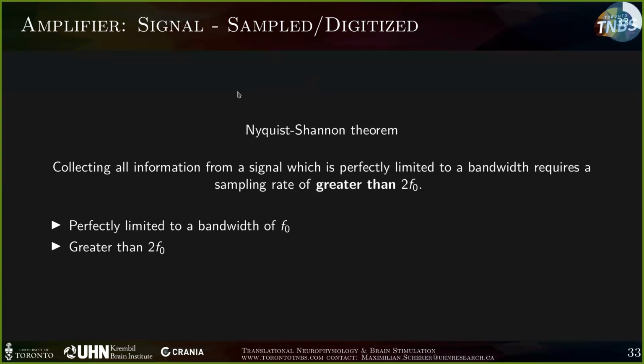And the other issue is that you have to select a sampling frequency greater than 2 times the highest frequency you expect in your signal. Not equal, like it's stated in at least 80% of the literature. It has to be greater than. Equal does not suffice.